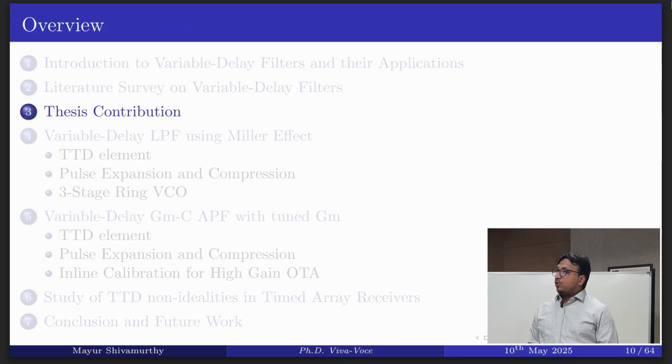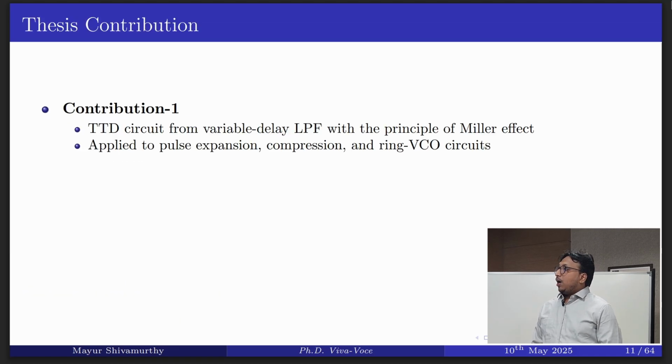Next we'll come to the thesis contribution. The first contribution is, right now we have seen that most of all the TTDs are realized with an all pass filter. For the first time we have explored how a low pass filter can be used in the realization of a TTD circuit using a Miller effect. The same principle will be further extended to other applications such as pulse expansion, compression and ring VCO circuits.